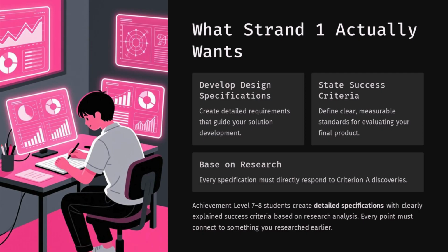What makes a good specification? When we talk about a good specification, here are the things we are looking for. 1. It must be measurable. Every statement must be testable later. Avoid nice, cool, beautiful. Use measurable language like size, cost, weight, material, color, durability, and number of features. 2. It should be clear and precise. No vague statements. No "should be durable", but rather say "must survive 3 accidental drops from 1 meter."